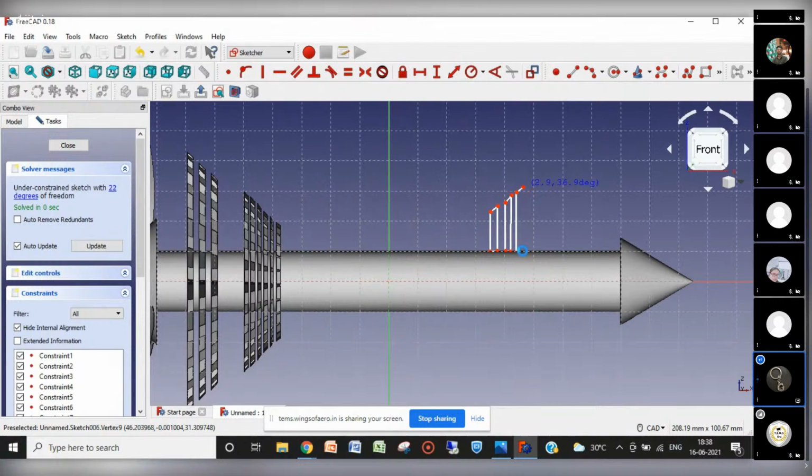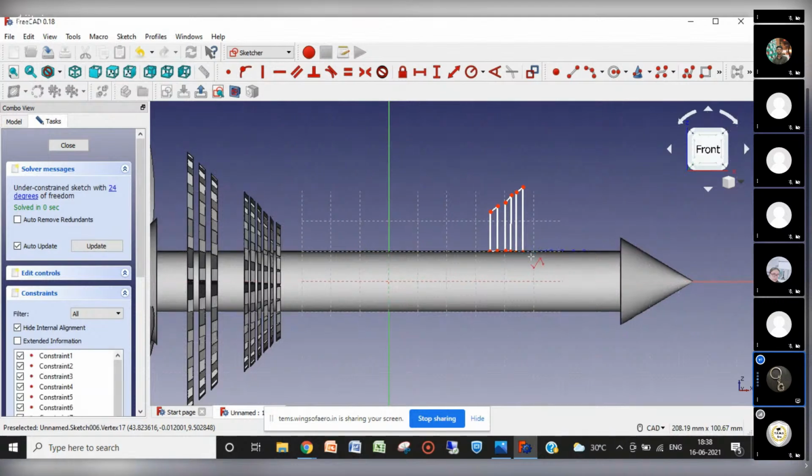If you want to ask the difference between jet and turboprop engine, there is not much difference. Just a propeller is ahead, which will allow more amount of air to enter the engine. In the jet engine, there would be just a simple compressor type fan there, which sucks the air inside. With this extra propeller, it will suck a little more air inside, so giving some gap, and further there will be low pressure turbines.